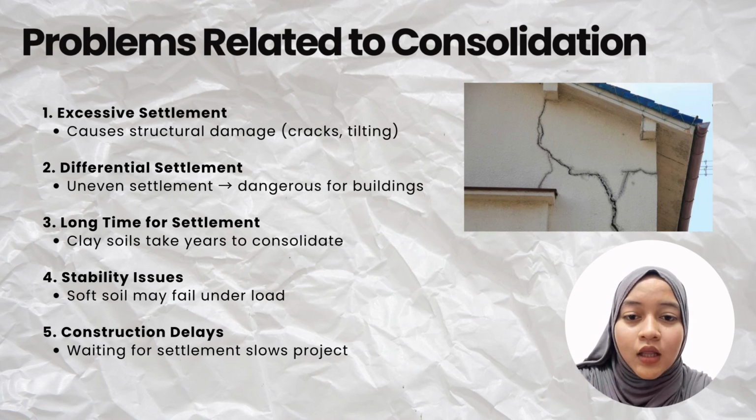The third is long-term settlement. Clay soil takes a long time to consolidate, so settlement occurs slowly over a long period. Next is stability issues. Soft soil has low strength and may fail when subjected to heavy loads. Lastly is construction delays. Construction projects may be delayed because time is needed for the soil to stabilize before continuing work.